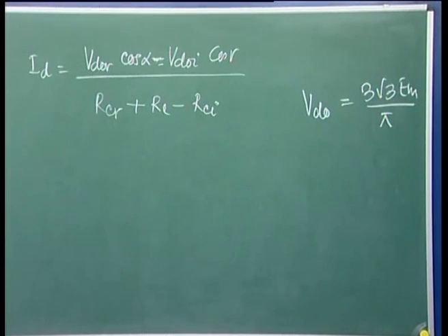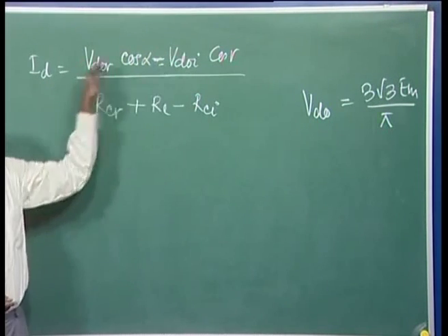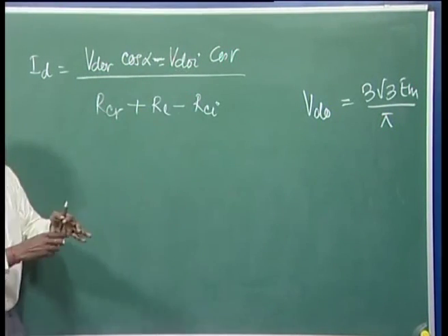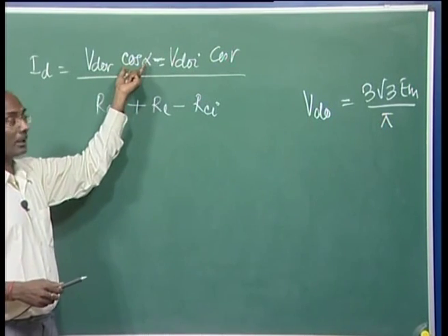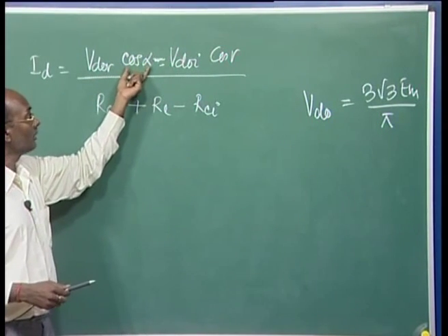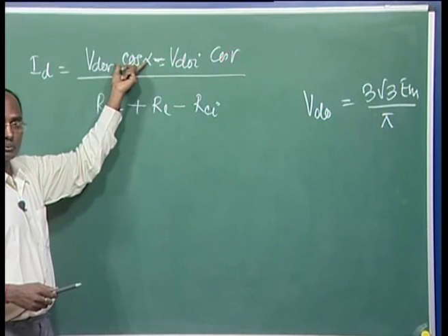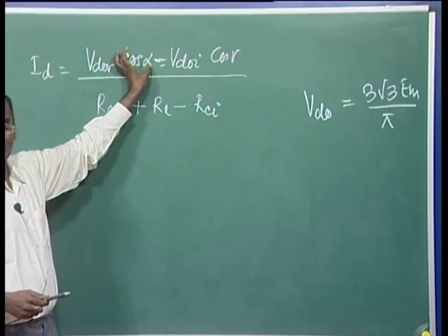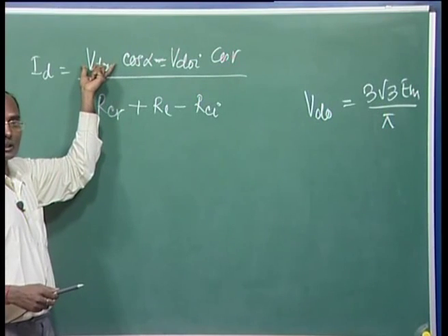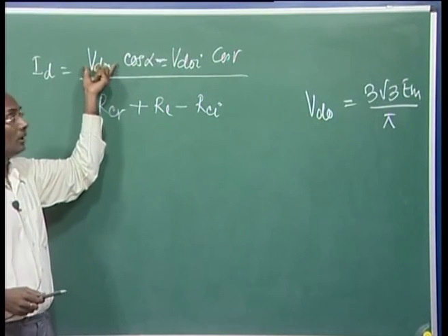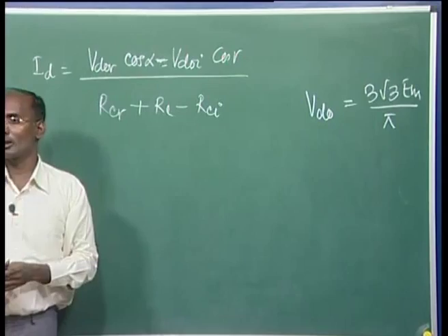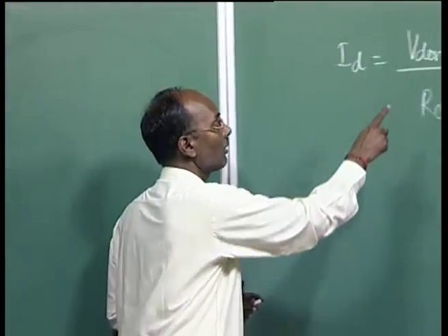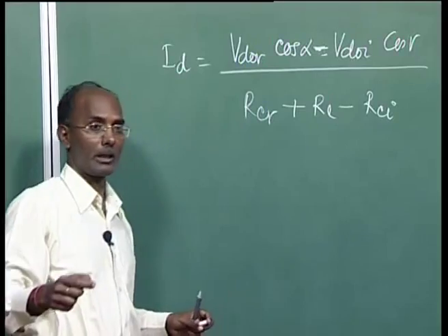If it is changing, now you can see the current is decreasing. Due to this increase, what will this controller try to do? This cosine should also increase, because we are not operating this one since this is slow control. So it will try to increase, which means your alpha will go to the minimum side, and it will be restricted when alpha reaches the minimum degree, maybe 5 degree.